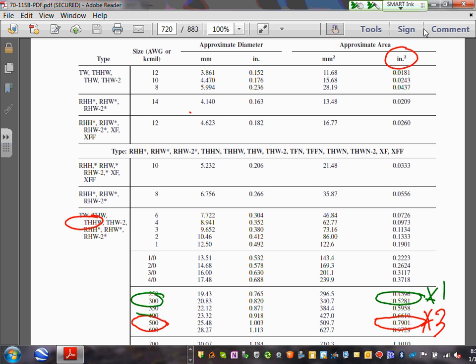Any question? You have to learn how to size a conduit, guys. Must. You know. Any comments? Any questions? Quick review of sizing conduits. You find the cross-section area. Now, when we added them up, Adam, we came up with 2.9 square inch. That's the value that you need.